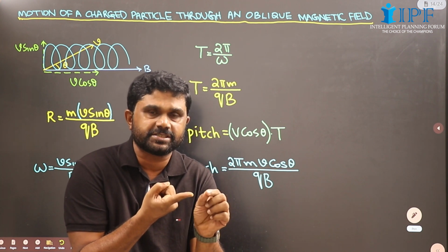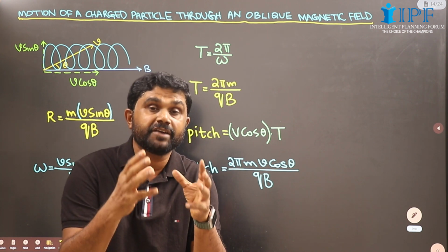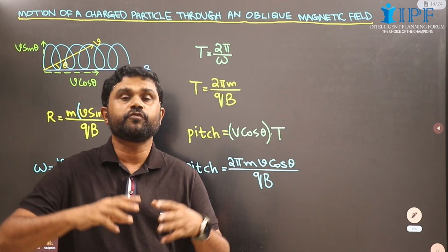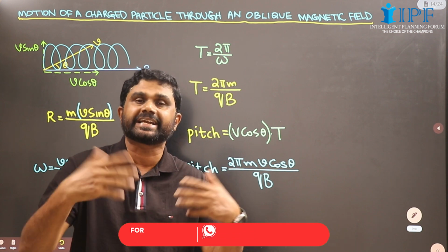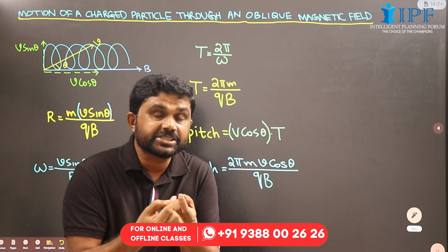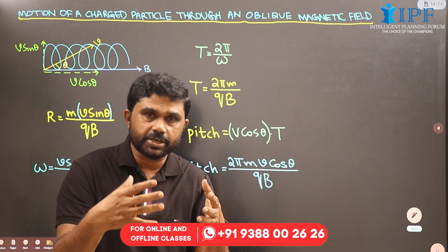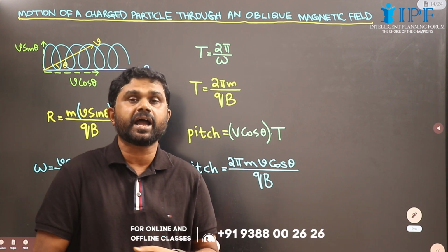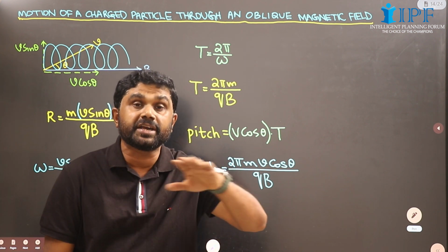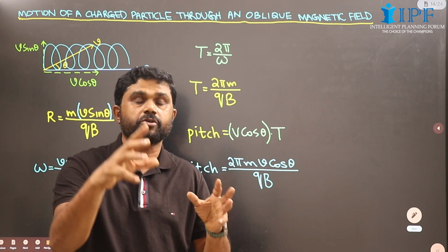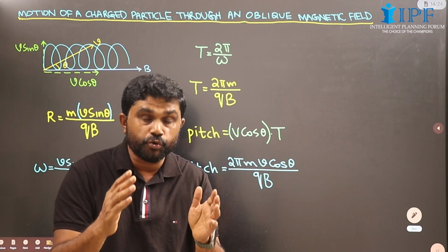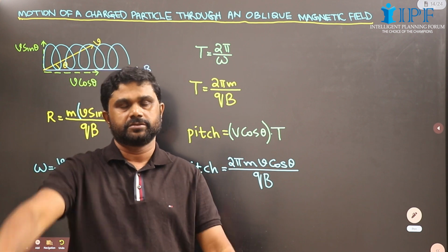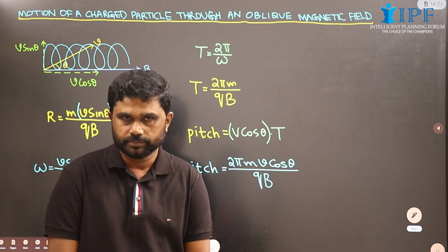Now if we give one complete rotation, the distance through which the tip of the screw advances may not be enough to measure. So what we usually do is turn it 5 times or say 10 times. Then there will be a measurable distance. That distance will be divided by the number of rotations so as to give the distance through which the tip of the screw advances in one rotation, and it is called the pitch of the screw.